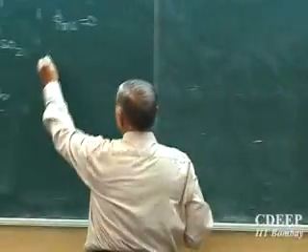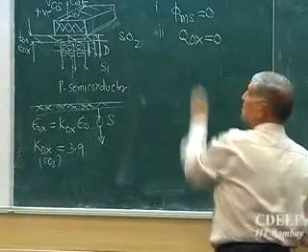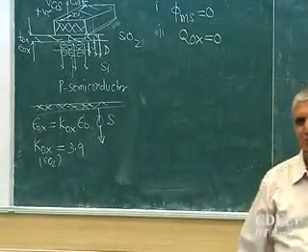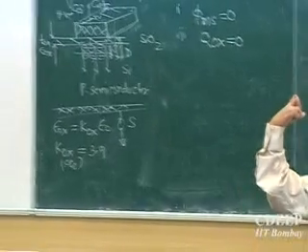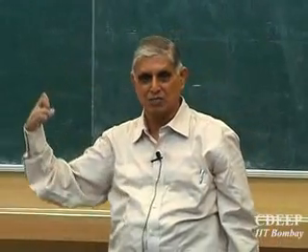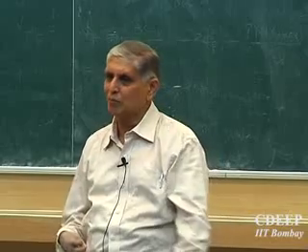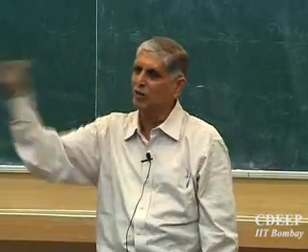And the second assumption we made is there are no charges in oxide. This also is charge density. Please remember, unless stated otherwise, it is all per unit area, because Cox is per unit area, so everything is defined in per unit area, so that Q by C is always V.